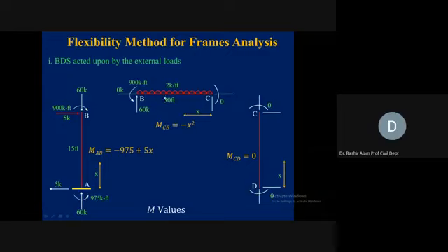So 2 times 30, which is 60. This total load is going to be balanced by B, and from B it can travel towards the support. So vertically, this member BC is in equilibrium: 60 downward and 60 in the upward direction. Horizontally, if this horizontal is 0 and here the horizontal is 0, so horizontally also it is in equilibrium.